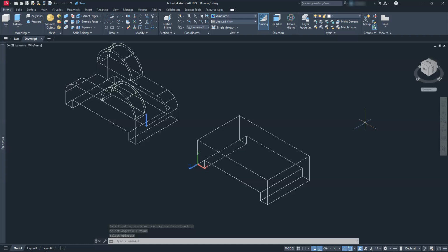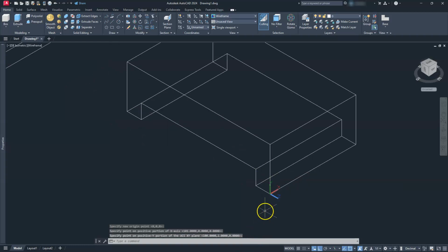Okay. If I want to do some math or things of that nature, I can also manipulate where my little hump is that's going here. Before I do that, let's work on this side. So let's manipulate our UCS facing this direction, and I want to put it exactly at this endpoint. So I'll go ahead and use the 3-point again. I'm going to place the origin at that endpoint, my X direction going that direction and my Y direction going up this direction. All right, so now I've manipulated my UCS.